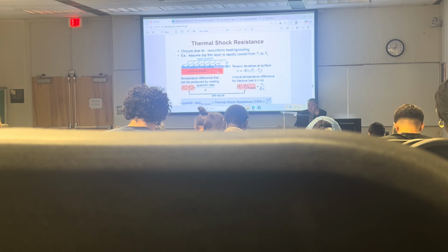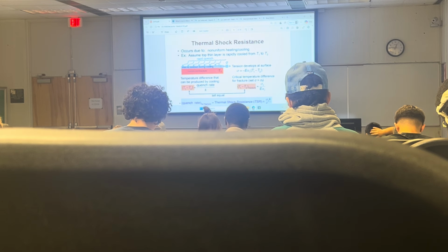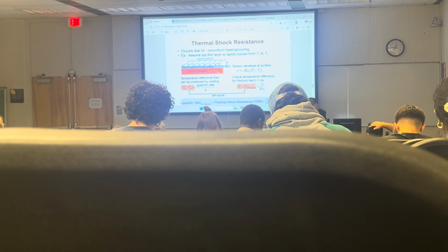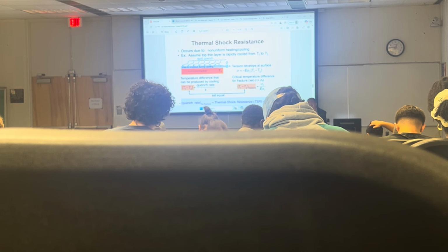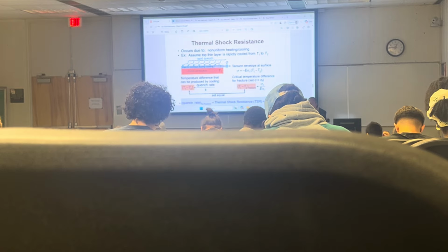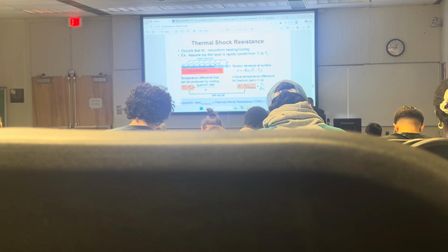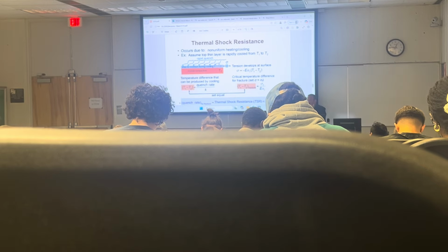So, what is the difference in the temperature on the skin, the surface, versus inside? Obviously, the one on the surface is going to be colder, right? And what happens to the materials when they are subjected to lower temperature? Do they expand or do they contract? They contract. So you have the surface layer that wants to contract. It wants to shrink. But the core is still hot at that particular moment in time.